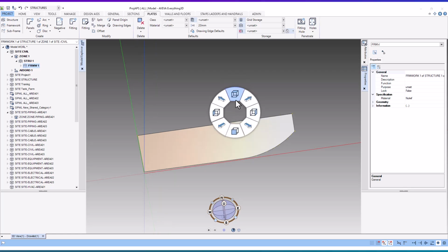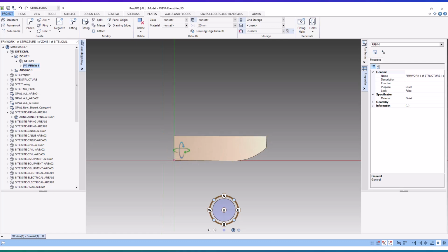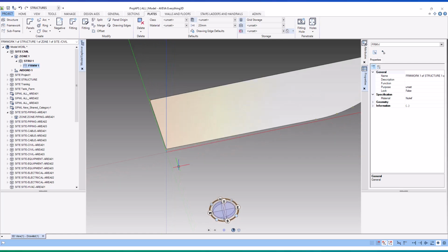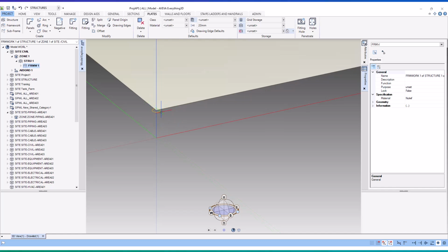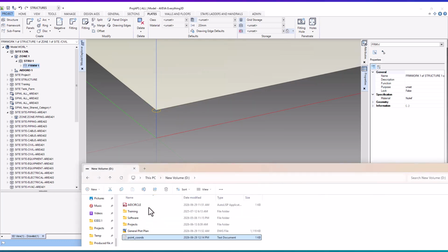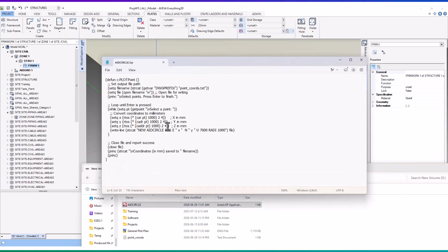One important point to remember is the elevation of the panel. The ground elevation should match the values specified in the plot plan. Instead of editing the elevation later in E3D, you can simply enter the desired elevation directly into the Autolisp routine before generating the coordinate file.